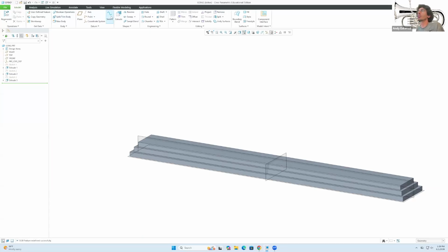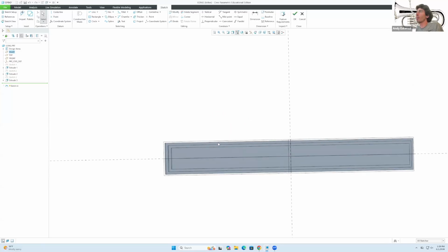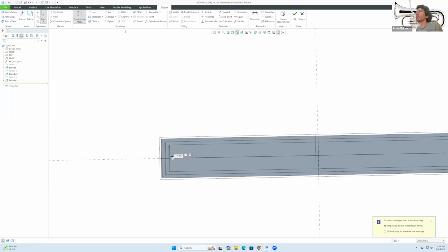So I'll go here to Sketch, this face. Okay. So now we're going to draw. Actually, this is the example that we did at the very introduction. Suppose I wanted a rectangle that is roughly there, and another roughly there. So I'm going to select these 2 lines, and I'll make them equal. There we go. And now suppose that I wanted that to be 15 as an example.